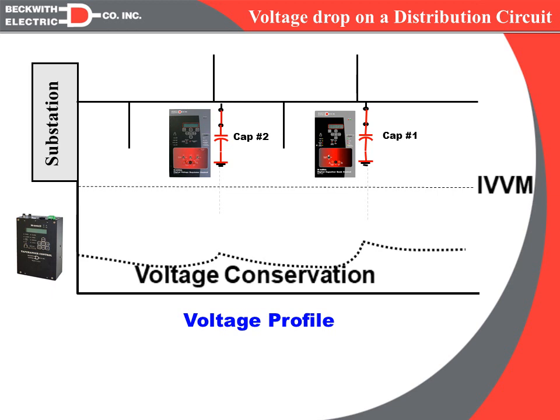One other comment to make here is that one of the trends is for utilities to start to want to run slightly leading on their distribution systems. In previous years, most utilities' goals were to be somewhere between 0.96 lag and unity.